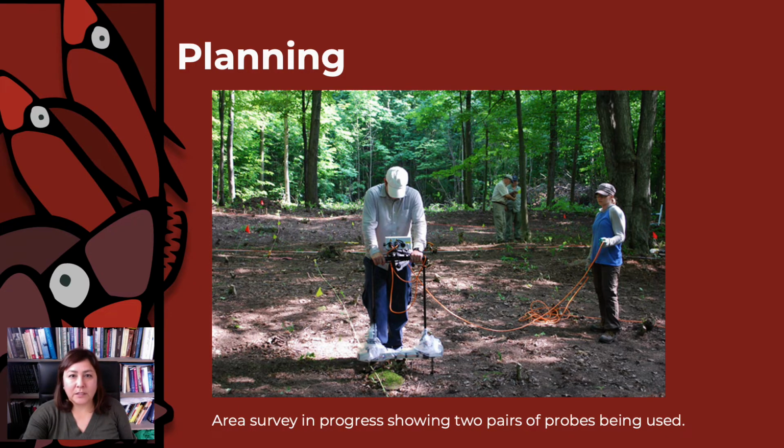There are two main types of resistivity survey. The first kind is called an area survey that maps a large area with a focus on a particular depth range. The second is called electrical resistivity tomography, or ERT, that images a vertical transect through the earth along a profile. Both methods have advantages and disadvantages, and the cost and/or time required can be different.